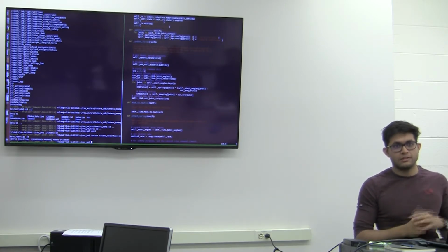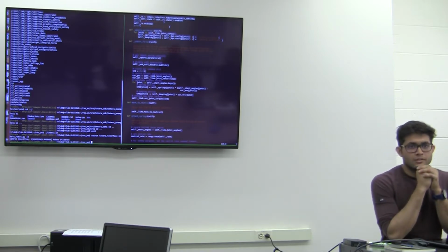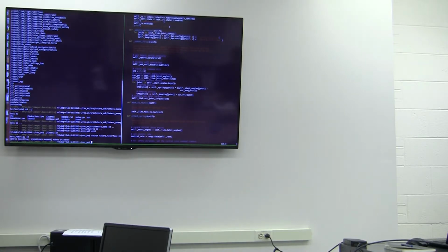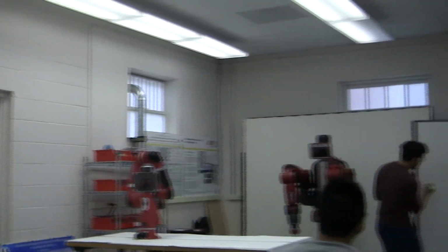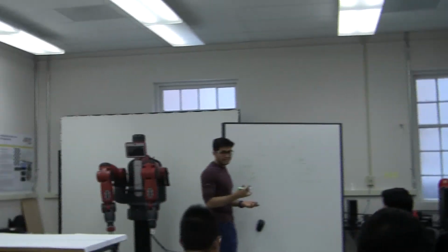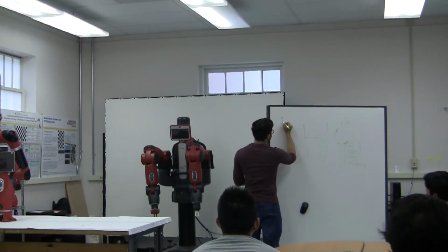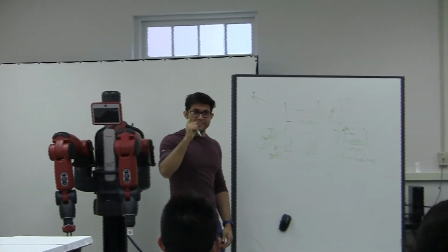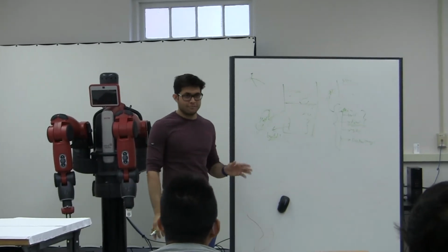It could be a fixed joint. It could be a rotational joint. But how will we tell the position? First of all, in URDF, you always know the parent link and child link. Do you know about that? So there's the parent and there's the child link. Each child can have only one parent, and each parent can have as many children as possible. That's very important, because you're going to mess up that part.